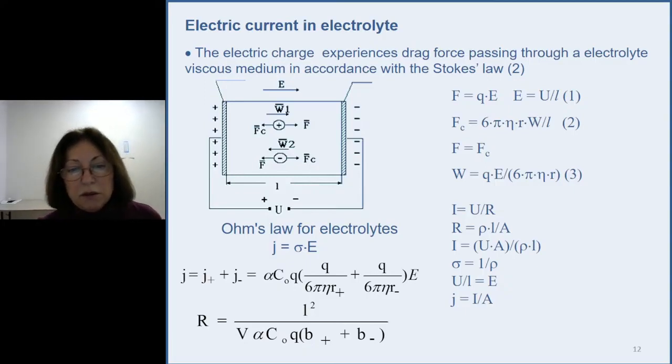So we can say about the electric current caused by this voltage applied and influenced by the resistance of the conductor. One more time, we use the formula to calculate the resistance of this conductor. In this particular case, the cross-section area of the conductor is the area of the plate, and the length of the conductor here is the distance between the plates where the solution is placed.